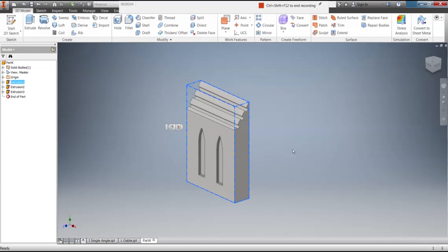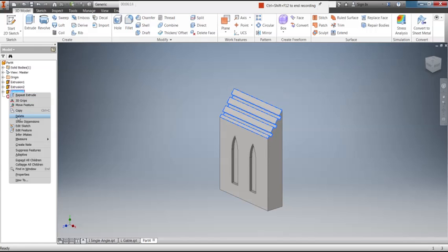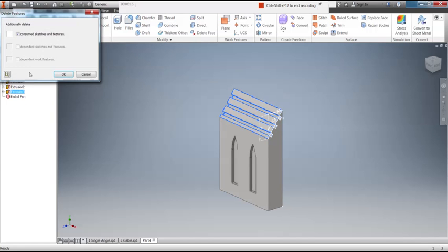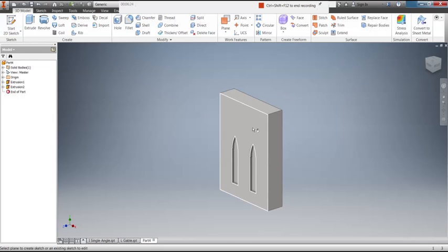But then what I'm going to do is come back here and adjust this piece for the gable top. So I'm just going to delete this previous extrusion I made. Now again, make sure you've saved it as the angle piece first. I'll go ahead and delete the consumed features and sketches. And now we can come back and make the gable. Starting a sketch on the front.